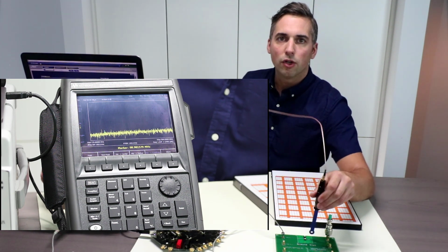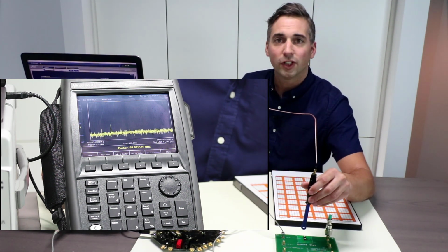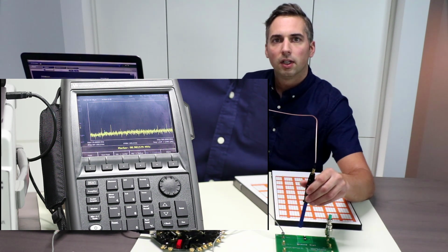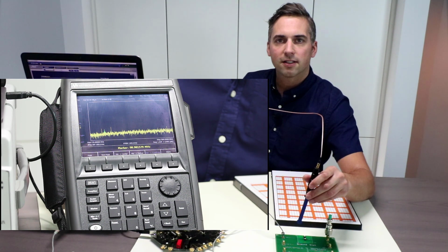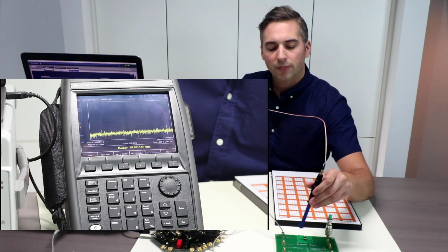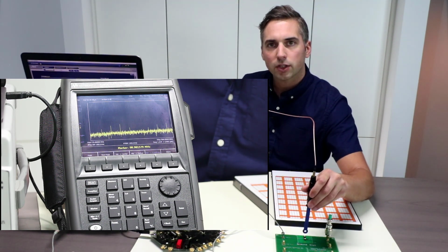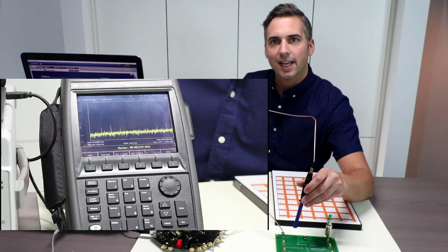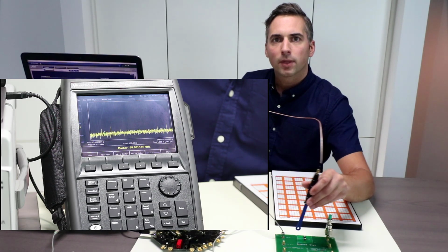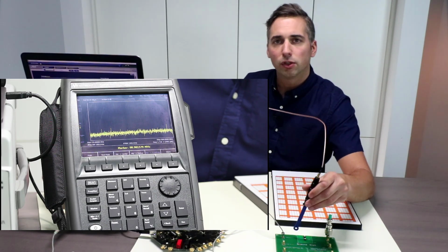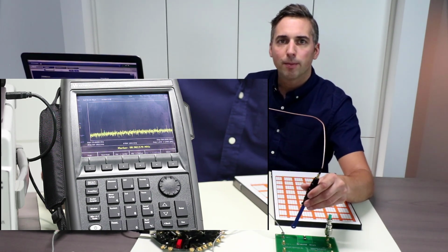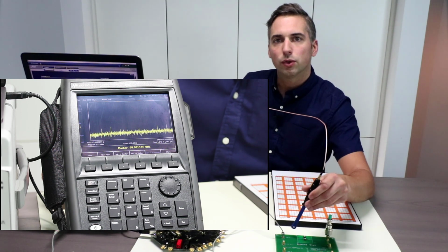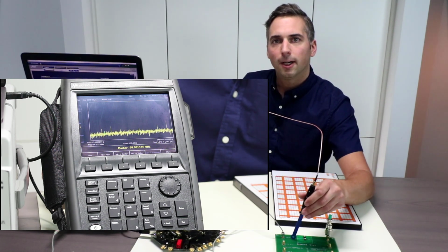So this is a big no-no. You want to avoid this situation at all costs. Now, on this board, we also have a couple of buttons that connect to the ground plane. It connects the ground plane much closer to the send path, and it allows the current to flow much closer to where it really wants to flow. And remember, that's the path that inherently uses the least energy.